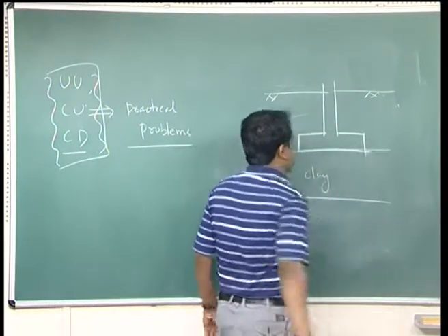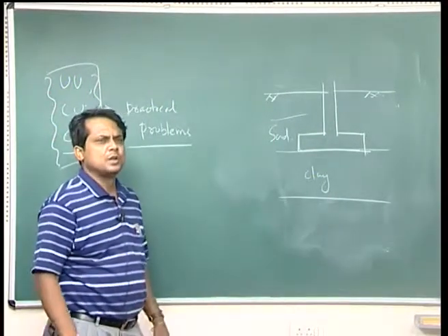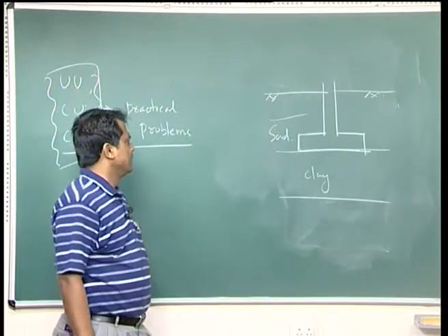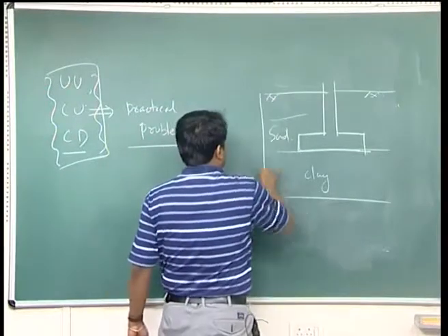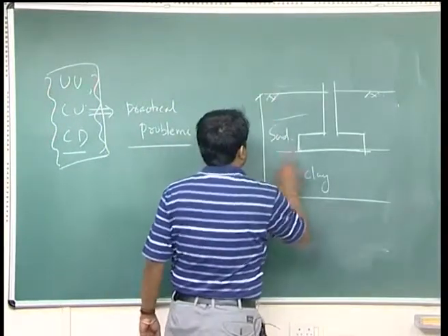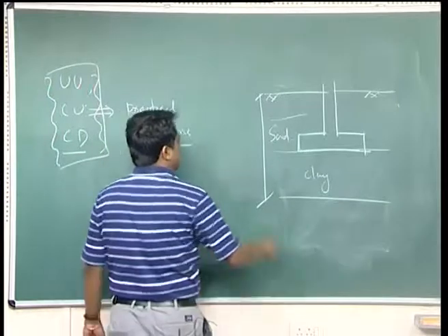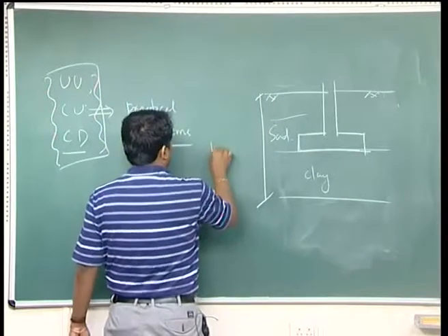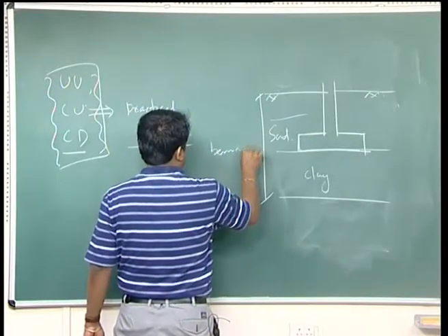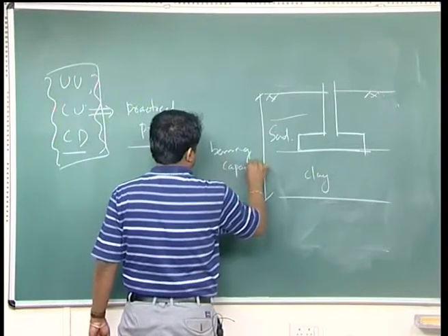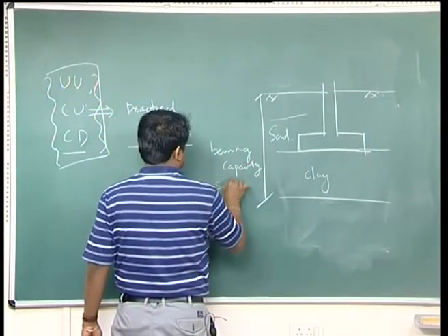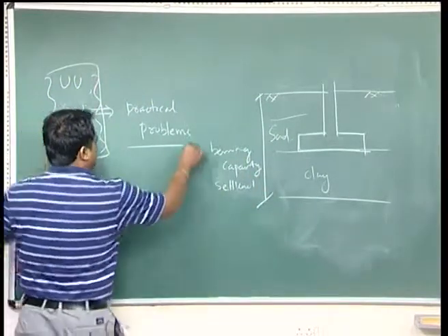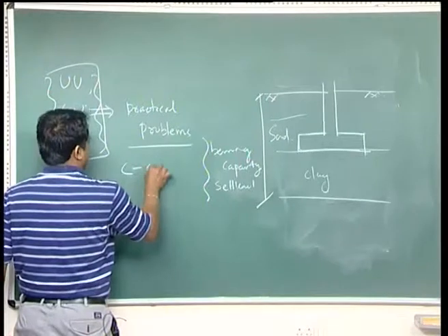over a period of time, say 5 years, 10 years, what parameter do you need to have so that this design can be done? So, these are all critical things, because once you identify the problem and the parameters required to calculate your bearing capacity and settlement, then you need parameters C and phi.